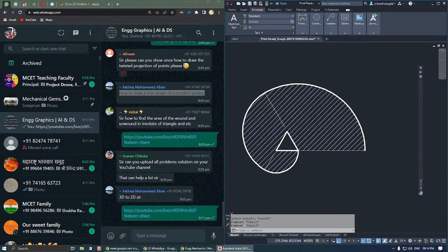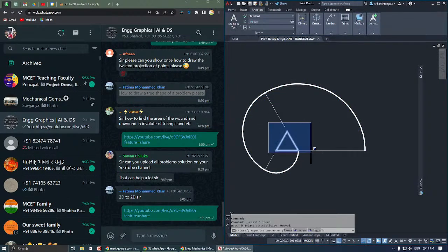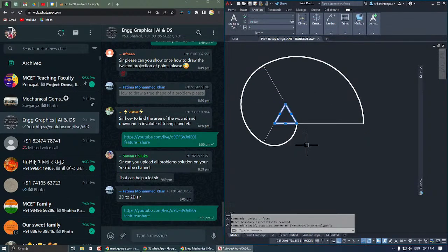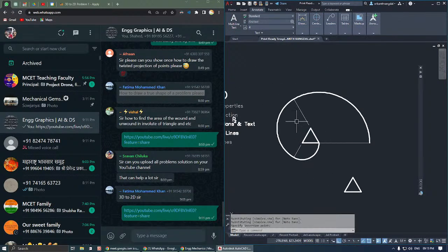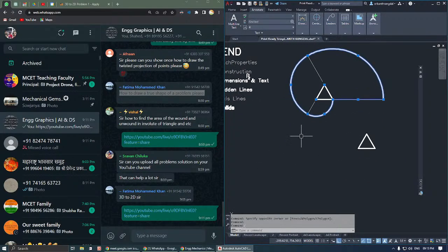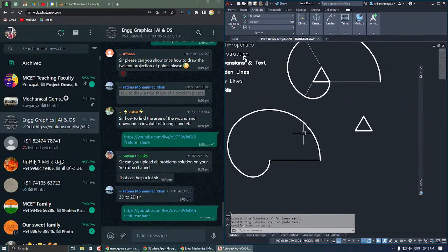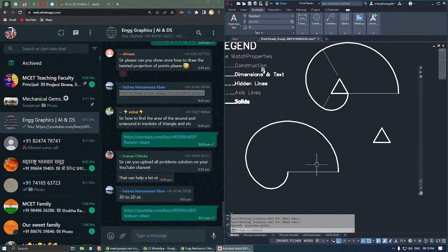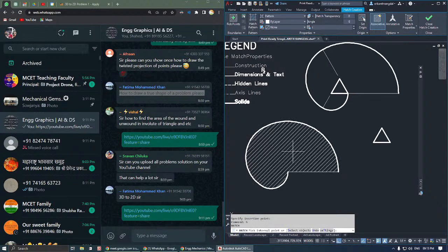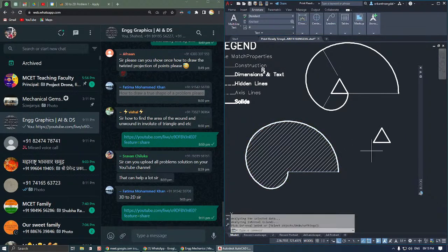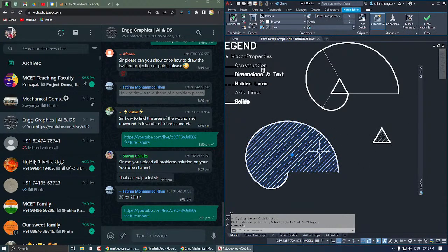So what to do with this? Now the workaround is to copy this aside, copy this entire thing aside. So this and this we need to take them aside. Then put hatches on this area and put a separate hatch on this area. Don't put the same hatch. When you select, both of them should be separate. So in one command I'm creating this hatch, in a different command, new command, I'm creating this hatch.